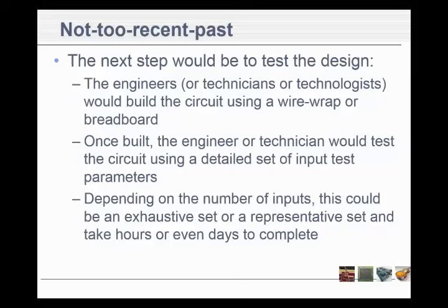Okay, so we'd put on the wire wrap, and the nice thing about that is it was pretty stable. It was pretty permanent, but if it didn't work, this tool would also let you go right in there and back it off and take the wire right off.